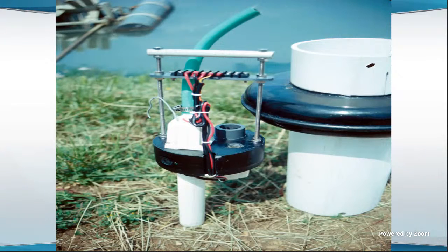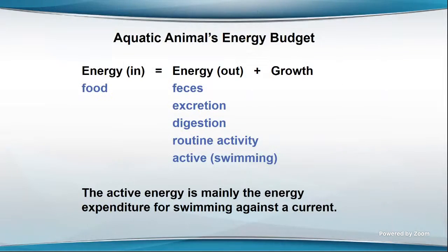Another thing to understand in these heterotrophic systems is that you don't have so much phytoplankton, so they require more oxygen from aeration, because there's not as much oxygen produced by the phytoplankton. And in most of those systems, they put a carbohydrate source like sugar or molasses in the pond, and that has a big oxygen demand, so you've got to add more aeration. So a green water pond is going to require less energy for aeration than one of those heterotrophic systems. But the heterotrophic system gives you much higher production from the same amount of water. So it increases the savings on land and water, but it requires more energy. We do need aeration, it has a major demand for energy, and we do need to increase the amount of energy used for aeration.